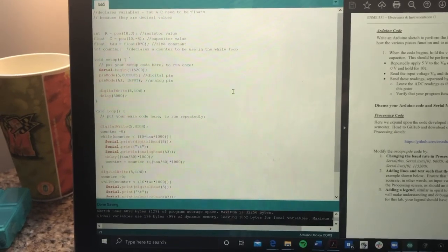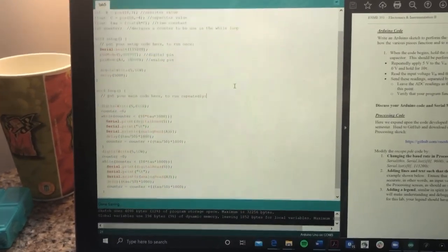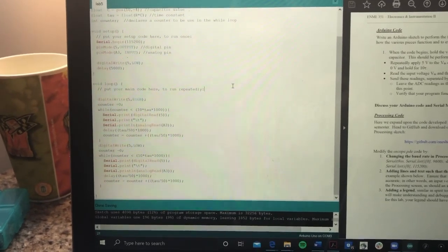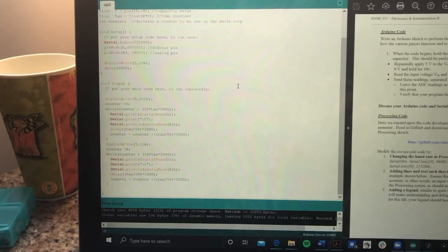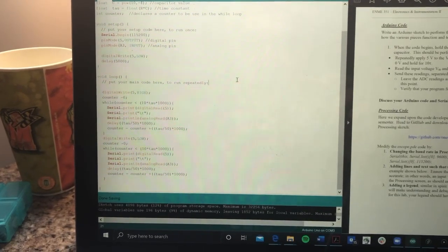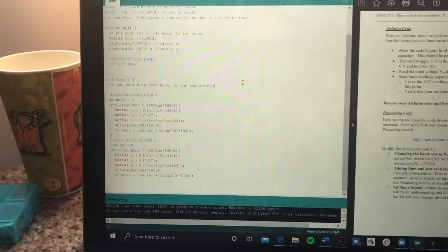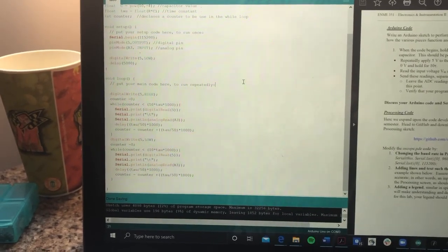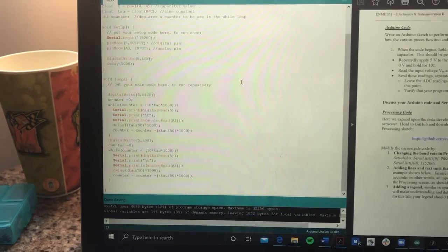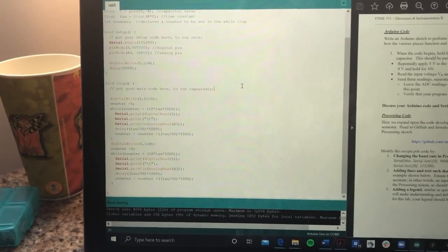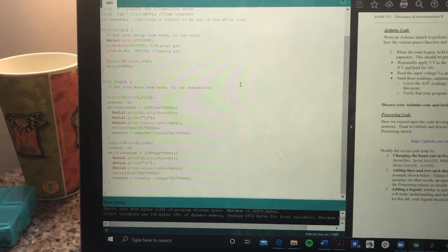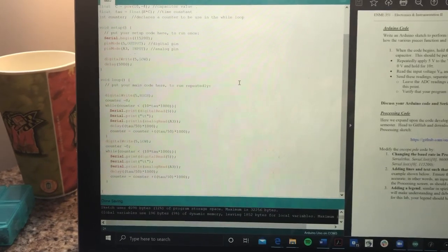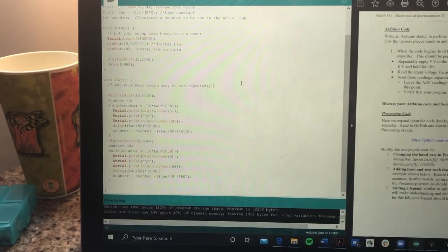And then we are using a while loop for this next part because while we are less than 10 tau for our time, we are going to read pin A3 and A5, and the while loop allows us to incorporate the other delay, tau over 50, once we are greater than 10 tau.